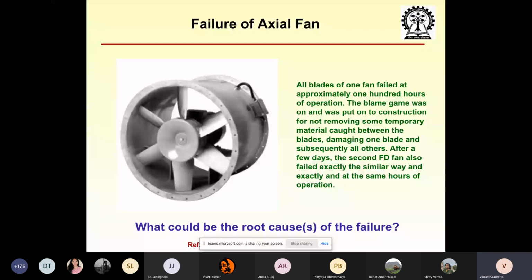But it's not just the shape vibration which is a problem here. Noise is an issue, but another major concern is that as it vibrates so much, the strains and the corresponding stresses will be very high. Now, what happens if the stress exceeds the yield strength of the material? Why is it not just undergoing some simple bent shape change? Why is it breaking? Once it overcomes the yield strength, there will be plastic deformation, and the fan blade could get stuck. Well, let it bend a little, let it deform a little.